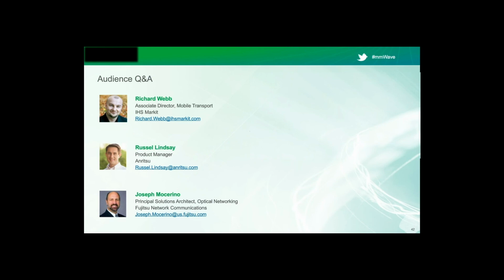So techniques for finding interference, obviously, there are several different types of interference. There's going to be a lot of multipath issues here. So utilizing tools that go beyond just throughput. There's a value in using UE devices to do testing, but UE devices are not going to give information on the directionality of signals, some of the higher level signal quality pieces, and then, like I mentioned, interference hunting. So using a tool like a real-time spectrum analyzer, with directional antennas, you can pinpoint where these are coming from with fast audio tools that give you audio reactions to power levels. You can then track them down, triangulate on those signals. We also offer tools like a mobile interference hunter, where you can do drive testing to pinpoint and triangulate interference, go find it, and then identify that source and have it rectified.